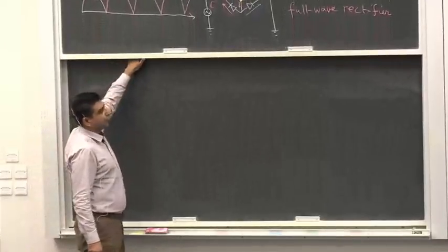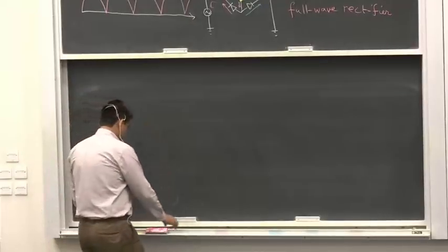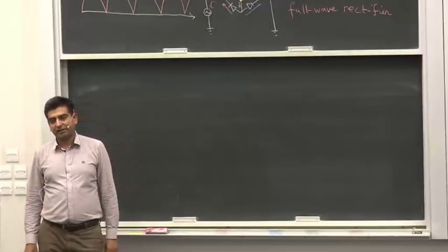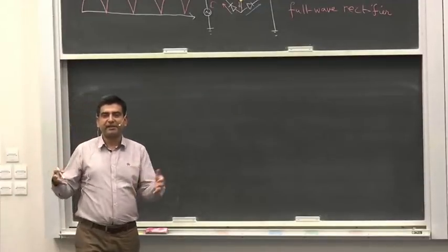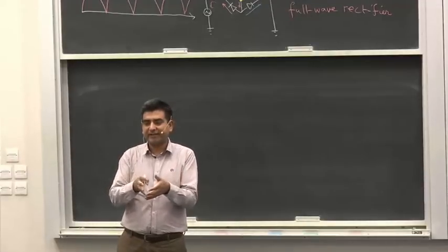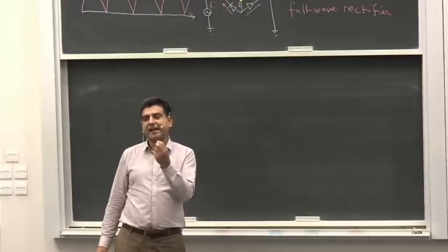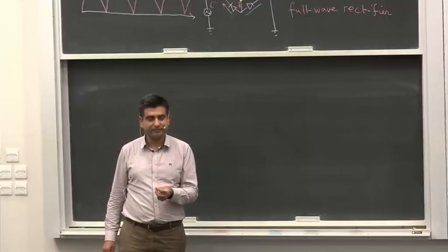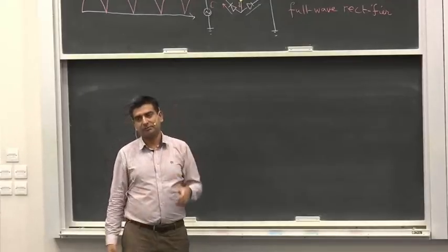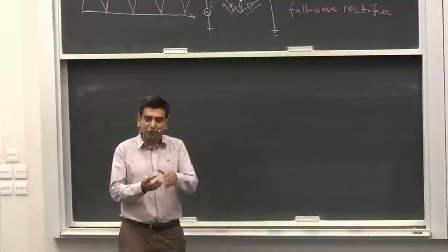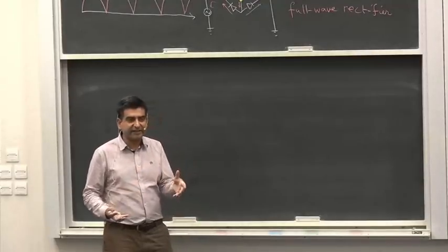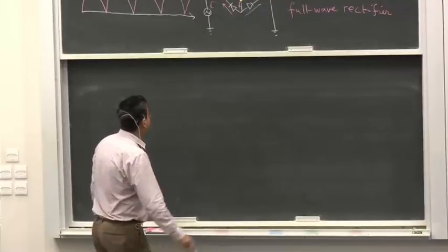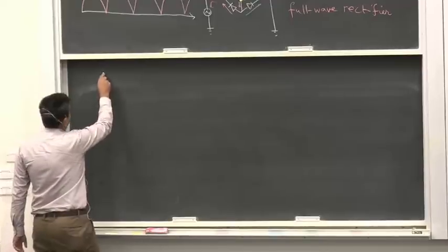So how is this diode formed? It's one crystal of a semiconducting material. You can't take a p-type material and graft it together with an n-type material and form a diode. This diode is constructed from a single crystal of silicon, and this crystal is grown. There are different techniques of growing crystals. One of them is called the pulling technique. The key idea is that you have a single crystal of silicon,